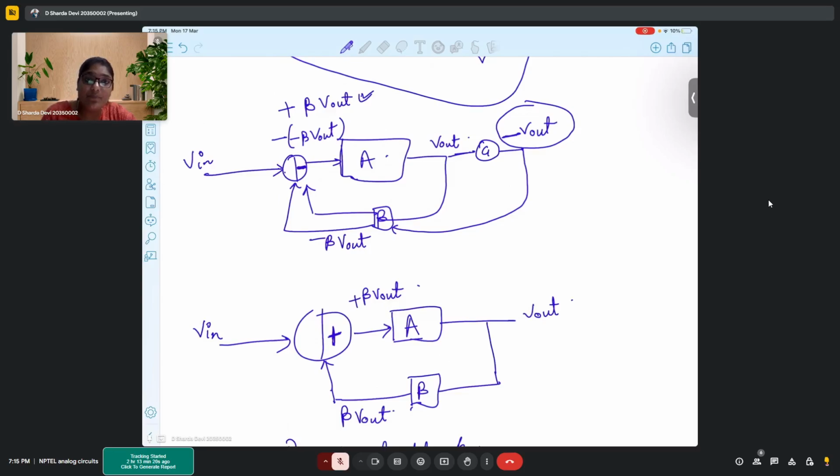Madam, there we are seeing only the small signal model. We don't know whether that transistor is an amplifier or a switch. Yeah, but you know the output, right? You know the impact, because it is given that in input you are getting V1, and in output it is extracting minus V1. And that minus V1 is translating to your V out, which is again being fed, right? So that 180-degree phase shift involvement can already be observed there. My doubt is, madam, we can see only phase shift, but for magnitude we can see the amplified version.